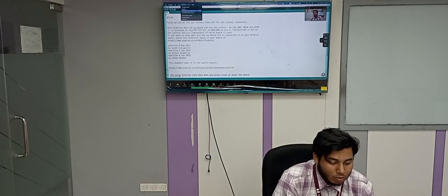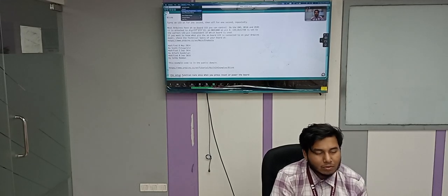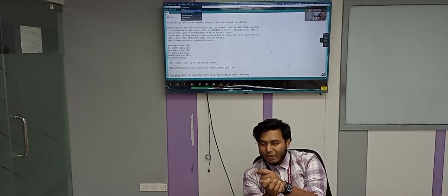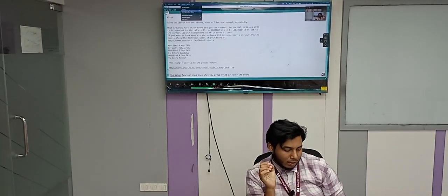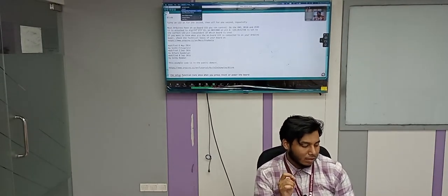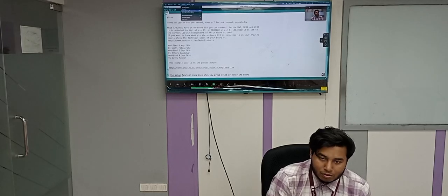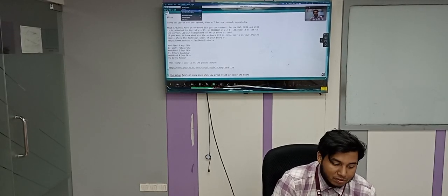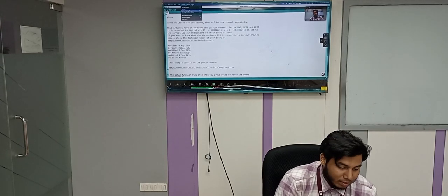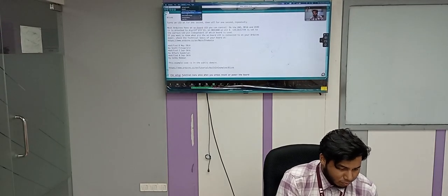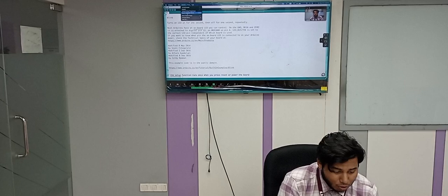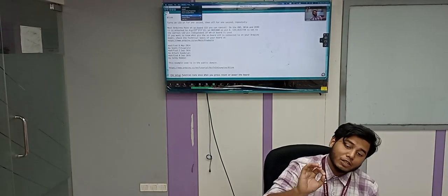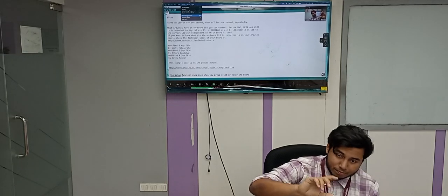So upload using programmer. I have talked about that you have an MCU like ATmega328P, but on the other hand, you can't select any port. So for that particular programmable ISP, you have to select this, upload using programmer. Okay, then export compiled binary is not so much important. Show sketch folder. The sketch would have been set to that portion.